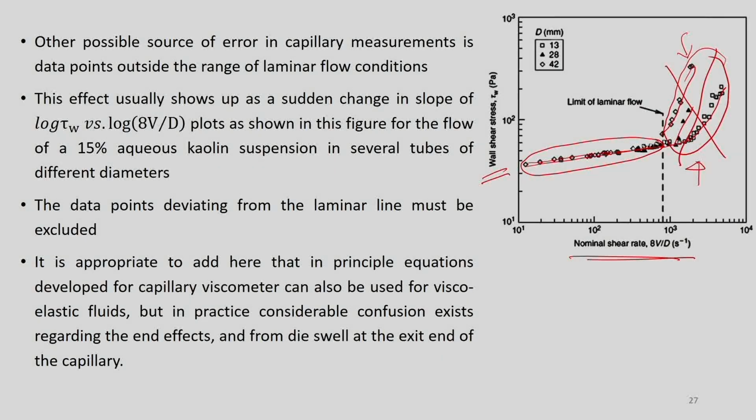Okay. So finally, it is appropriate to add that in principle, equations developed for the capillary viscometer can also be used for viscoelastic fluids, but in practice considerable confusion exists regarding the end effects and die swell at the exit end of the capillary. Though in principle the working principles of capillary viscometers can also be used for viscoelastic material, how much the L by D value should be, and how to incorporate the correction for the end effects etc., are not known for viscoelastic fluids.